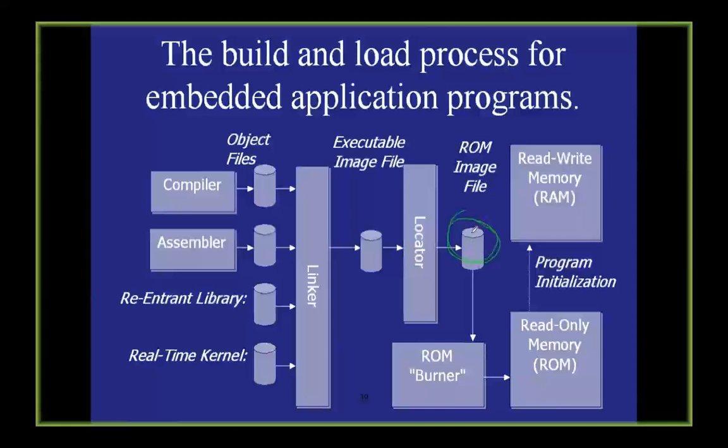This is my app, and it has to sit over here. We have to flash this using a utility, and a ROM burner will help me place it. So my application comes and sits over here. Whenever power is on, traditionally that application will be copied to the RAM area and will execute.